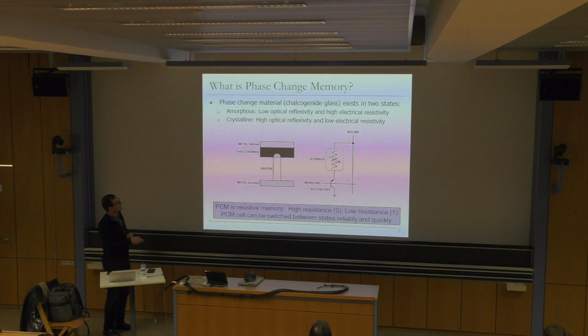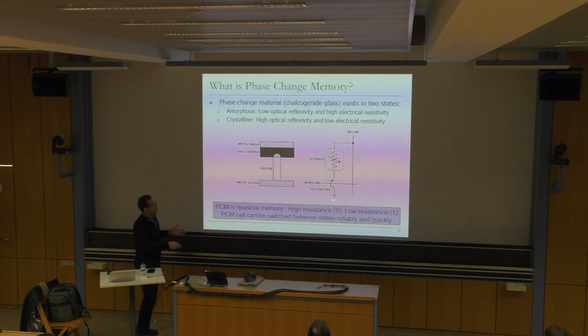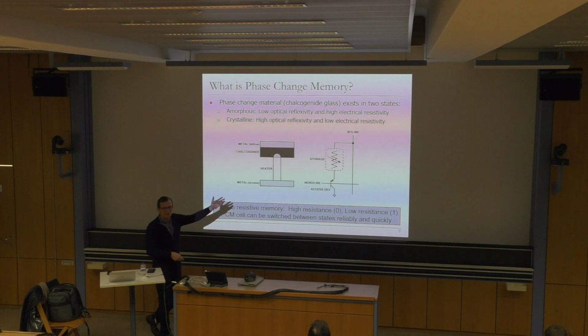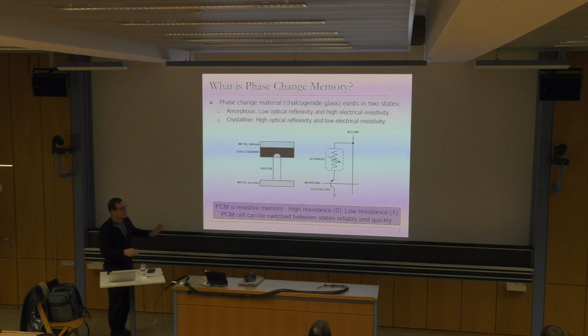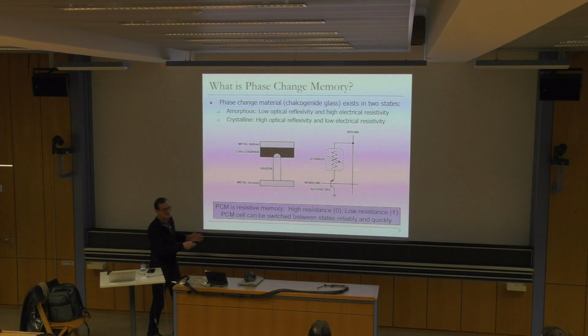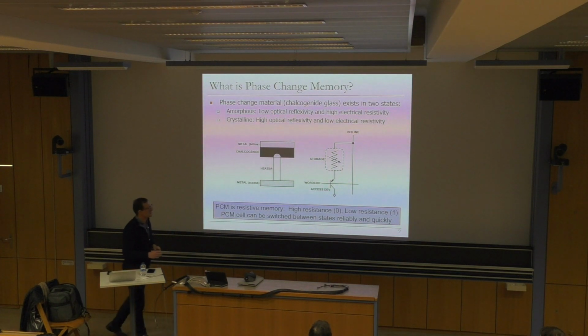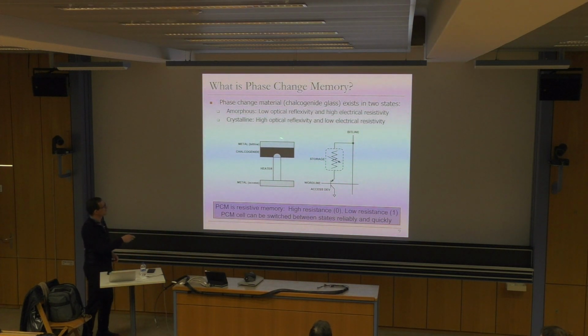So you can see the bit line and the access word line, and a heater and chalcogenide glass over there. Okay. And once you abstract it, it kind of looks like a DRAM cell in the end, right? Once you abstract any memory technology, you have a storage device and an access device, which depends on the abstraction level you're looking at. But if you go inside, the device may be very different.